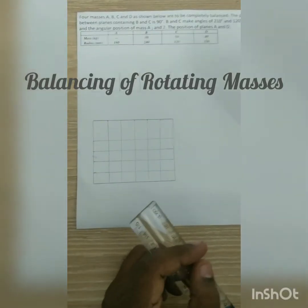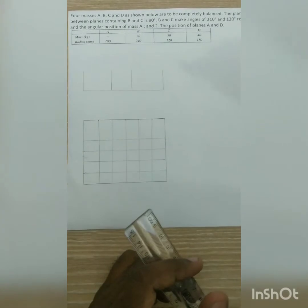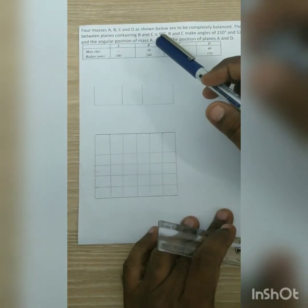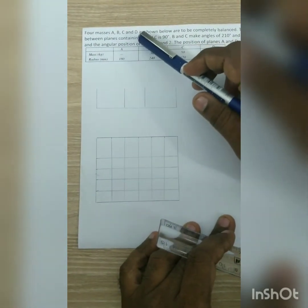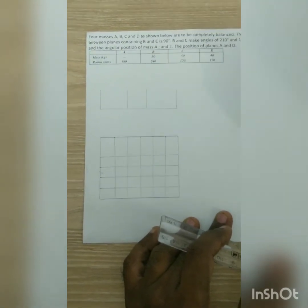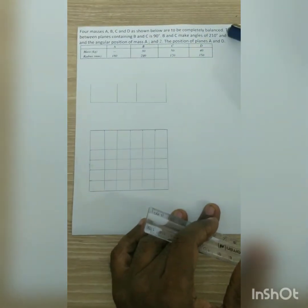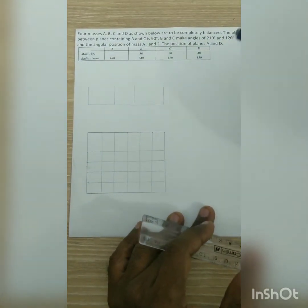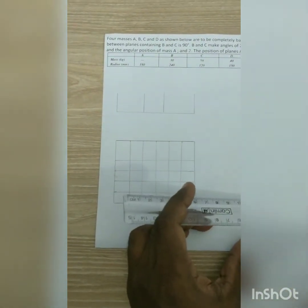This is a problem on balancing of rotating masses at different planes, and in this problem I can see that it is given that the four masses A, B, C, D are completely balanced. They are not asking us to balance. They are saying that it is completely balanced and they are asking to find out the unknowns. So now we are going to represent A, B, C, D.